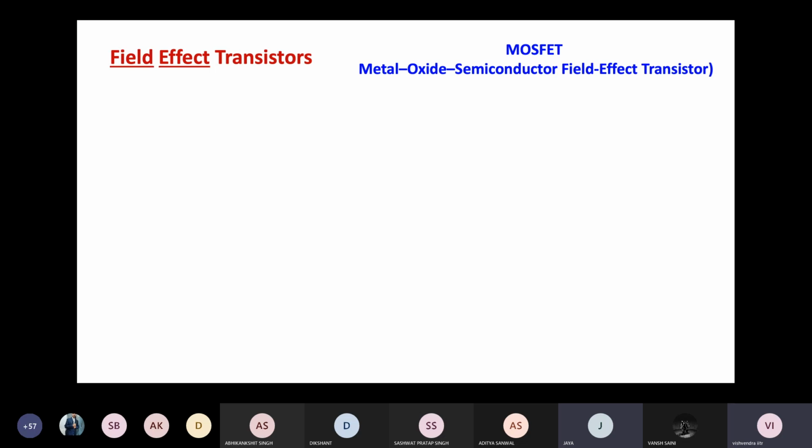Even in our cell phones or laptops, almost all the transistors are MOSFETs. There were good reasons for that. One was that a large number of MOSFETs can be integrated on a single chip. This integration is easy in the case of MOSFETs as compared to the BJT. BJTs are also big in size because this depletion control needs to be done properly.